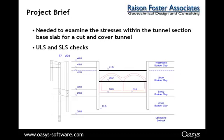Now, the geometry of the problem and the stratigraphy is shown here, but the interesting thing about using SAFE, and this goes back to your method of analysis, is that you're able to do ULS and SLS checks. So, for example, if you were using a limit analysis method, you would only be able to see the ULS behavior in this kind of problem, if you were able to model it at all. Whereas with SAFE, you could see how a structure would behave in a ULS and SLS condition.